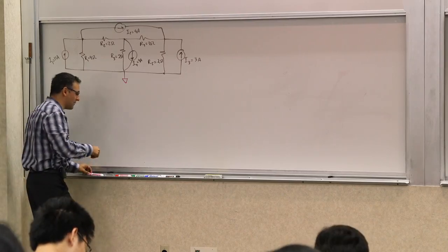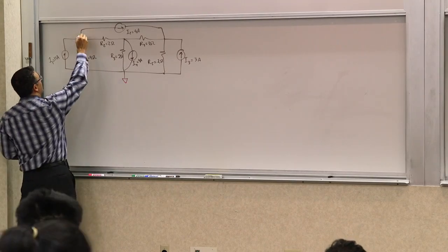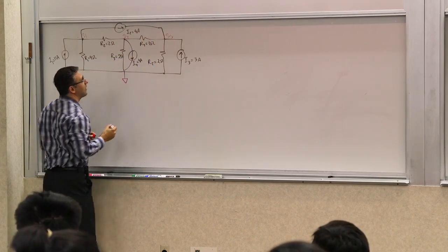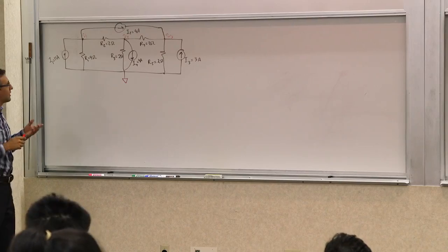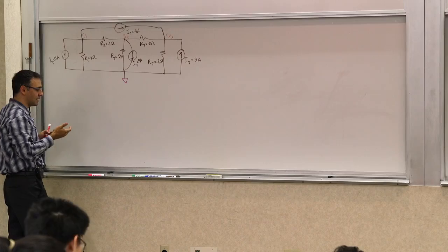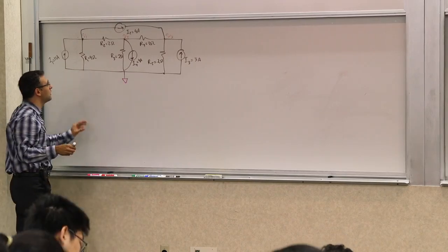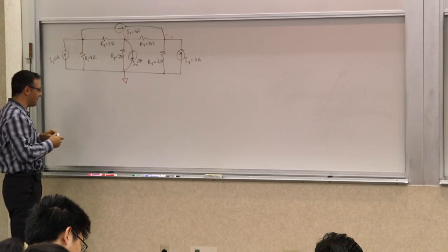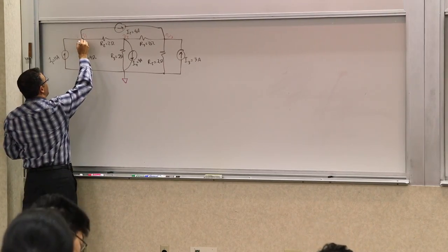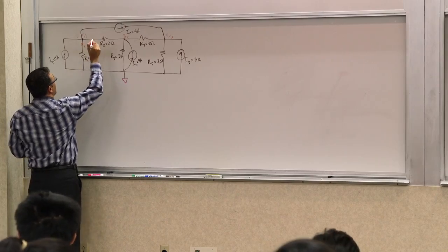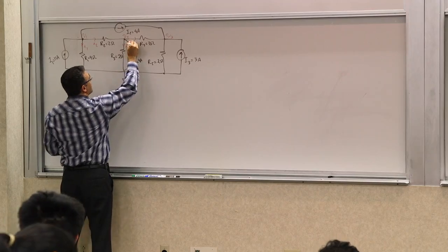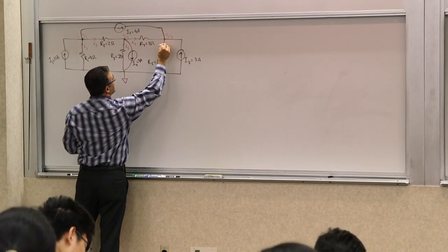So that's one, and then you need to define node voltages. We define V1, V2, and V3. There are really four nodes. One is ground, and there are three nodes whose voltages we will define. So if you were to write KCL and KVL for these things, we could do that, but let's write the KCLs one more time and see what happens. For example, on node 1, let's define this as current I1, current I2, current I3, current I4, current I5.